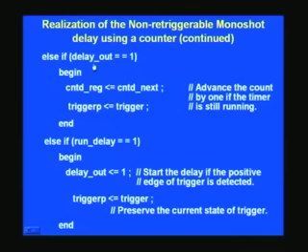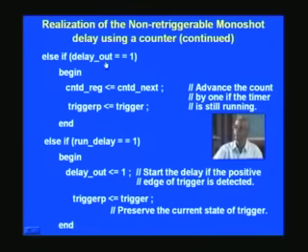Now we have another else if statement. First we sense the output, if it is 1. I mean, delay is not at 1, it will be 1 later on, but anyway we put this as the priority condition. If it is 1, we need to increment the counter, because this implies that once the output has become 1, the counter has started running.